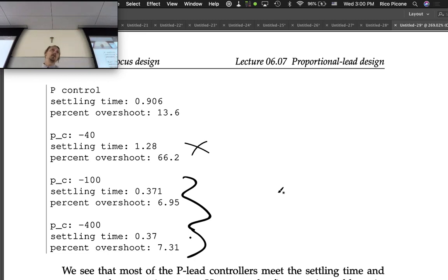But we didn't. It was close, and it happened to be on the good side of close, right? So we didn't get our settling time like 0.45, and we didn't have a percent overshoot of 13. That would have been not great for our results. So it was off in the right direction, right? It was off in the tighter direction. It was tighter to what we probably want in our design.